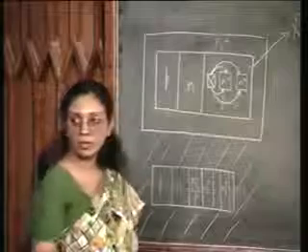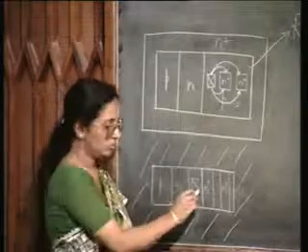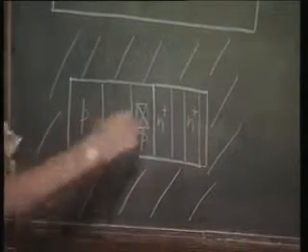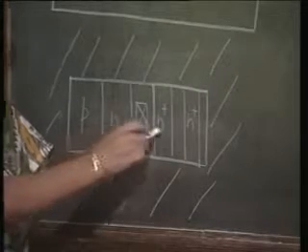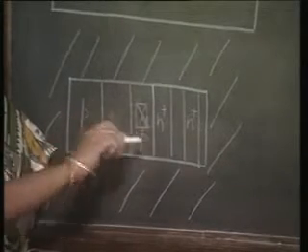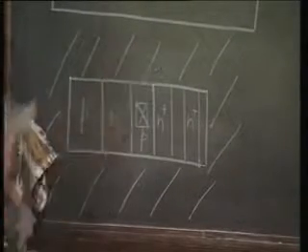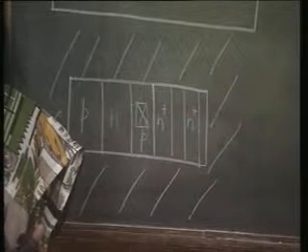In this case, however, how will the current flow? From this base to this first collector, it is not a problem. How about the second collector? It must flow underneath the first collector in order to reach the second collector, because I do not have any space on both sides for the current to flow, right.